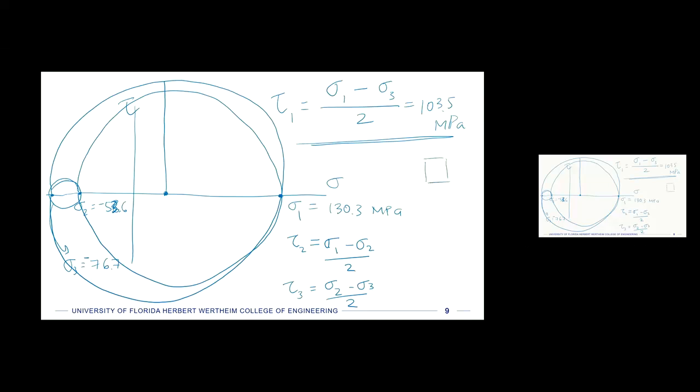If you're talking about 2D, then you have your little stress square, right? And then you can calculate the principal stresses and rotate it. And let's say you rotate it slightly like this to get the maximum normal stresses, well, we know that the shear stresses occur at 45 degrees to that, okay? And that comes from this math, but then it also comes from those tensile tests where you pull on a ductile metal and it always fails at 45 degrees, right?